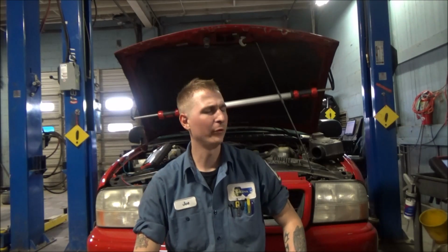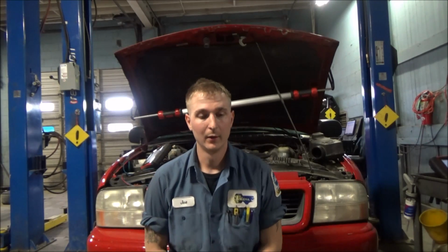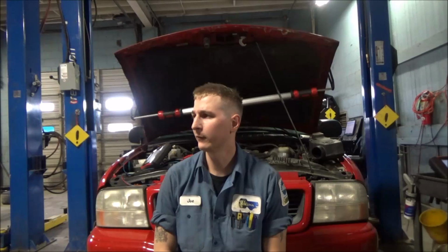So yeah, guys, we absolutely flew through that one. P0122 throttle position sensor circuit low voltage here on this 2001 GMC Sonoma. We very quickly attacked this. We had to do some minor tear down to get to it, no big deal. Some highlights of this, this is a 3-wire potentiometer, pretty standard for throttle position sensors of this vintage.